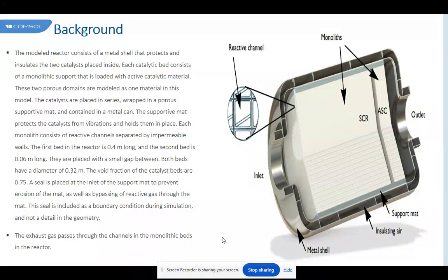Constant physical properties and uniform channel cross-section, and the steady-state bifurcation diagram. Before we present numerical simulations, we analyze the effect of the solid conduction on the steady-state behavior of the monolith using simplified versions of the above general model. We consider first the limiting case of zero solid conduction and uniform catalyst activity. Further, we make the assumption of constant asymptotic values for the transport coefficients, use a positive exponential approximation, and neglect washcoat diffusion limitations with this assumption.